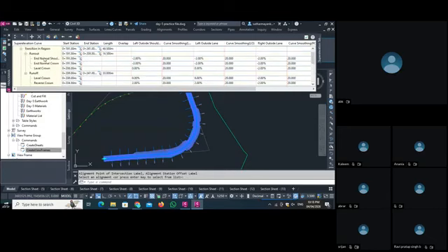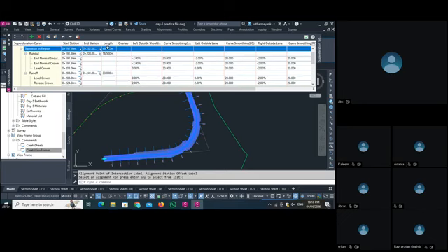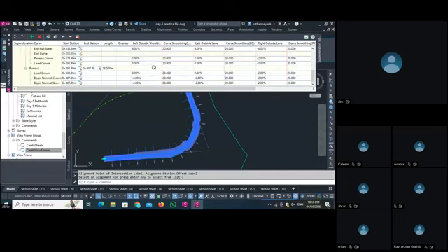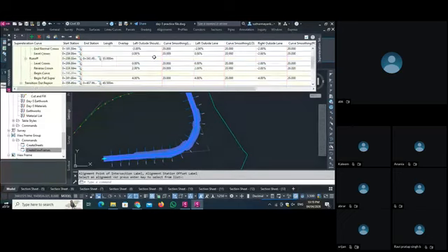See, as I click here, our station and the transition length will show. Then all the things, because if there is some mismatch, you can manage. We provided all the details of our shoulder detail and our slope detail, so there is no error here. As we set the design criteria as AASHTO 2011, there is no error showing here.